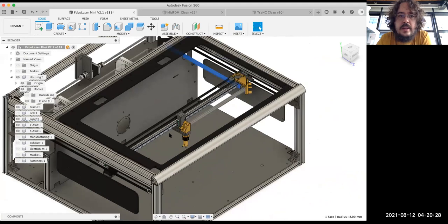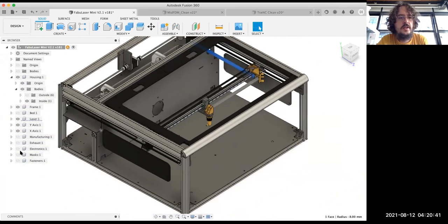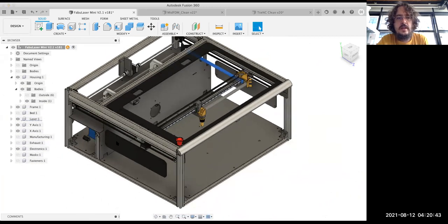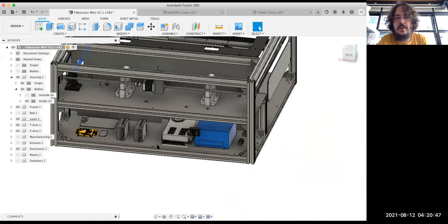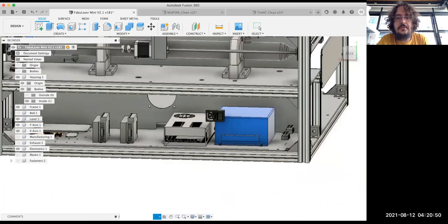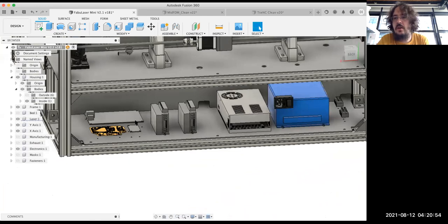And the linear guides used are quite fast. This kind of design, with one motor on the back and one motor for the X, is implemented in almost all laser cutters. So then the rest of the machine is rather easy. We have the electronics separated from the laser over here, with the high voltage on the right and the low voltage on the left.